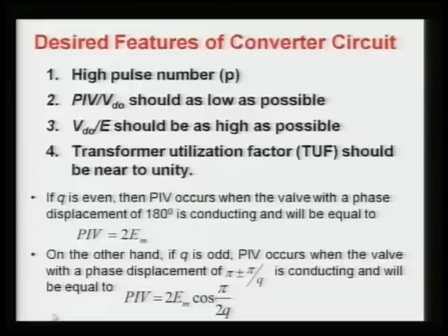Second is the peak inverse voltage, which is also related to the cost of the valve. If the peak inverse voltage is very high, then we have to go for very expensive valves, and therefore we have to keep it as low as possible. To make it general,